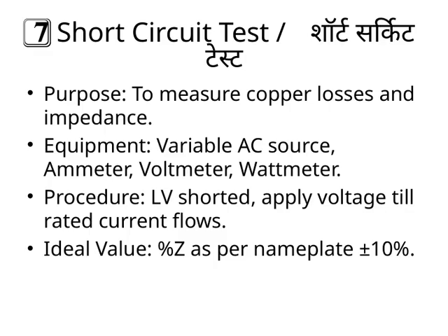Regarding the procedure, we start by shorting the low-voltage side, effectively creating a short circuit. Then, we gradually apply voltage until the rated current flows through the transformer. This way, we simulate the conditions under which the transformer operates when fully loaded.